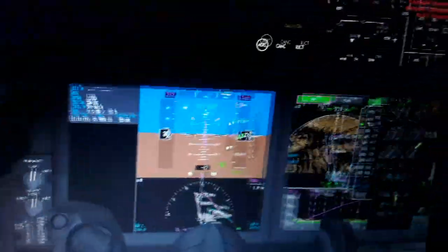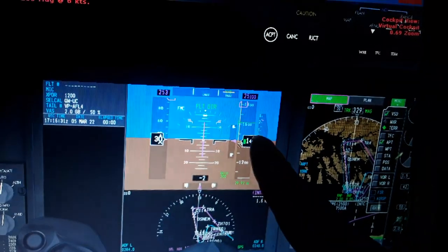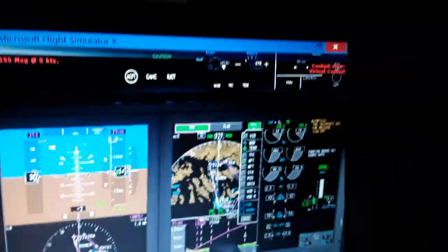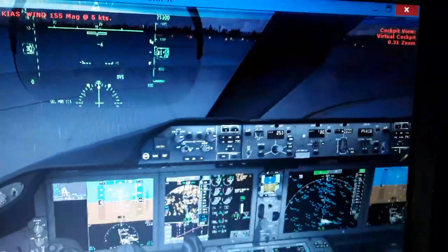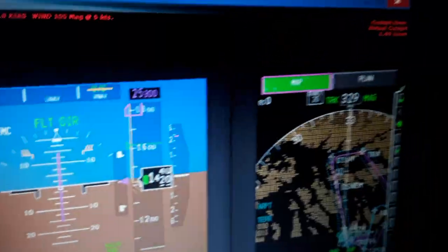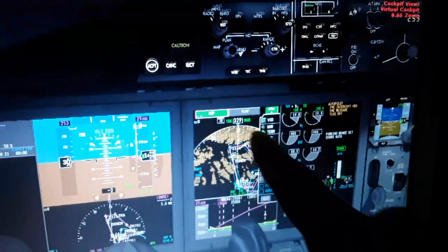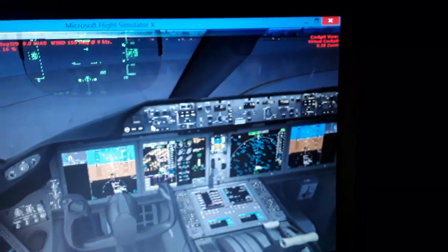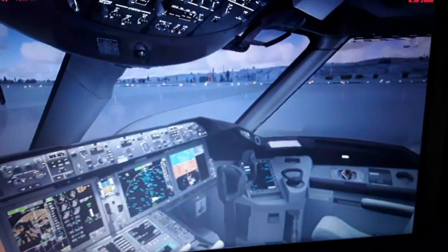So the displays are the pitot airspeed and altitude and rate of climb or descent, and also laser gyroscopes for acceleration or deceleration of the aircraft and attitude. So these are controlled from the air data computer, GPS position, terrain around you, angle of attack as you fly. So this is the air data you need for the flight instruments and navigation.